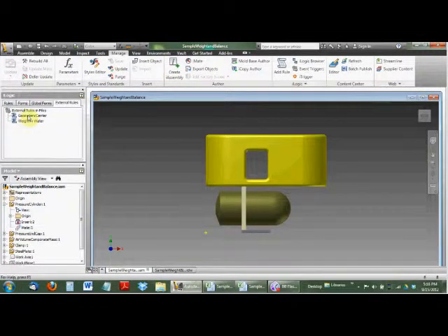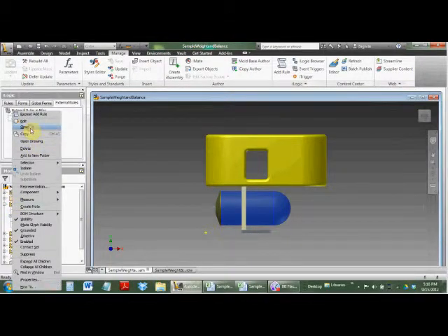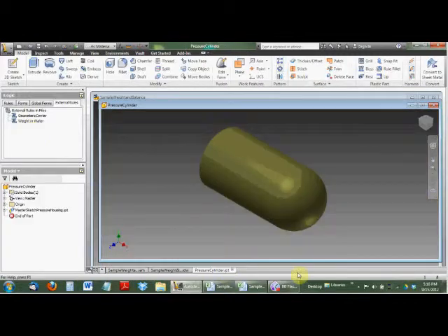I've included this iLogic geometric center rule, which I only include in the assembly, and then it puts itself into all the parts, and then into all those parts it basically creates a set of custom iProperties that are X, Y, and Z values that are relative to this origin right here. And I'm going to open one of these parts. Okay, I've opened this cylinder.